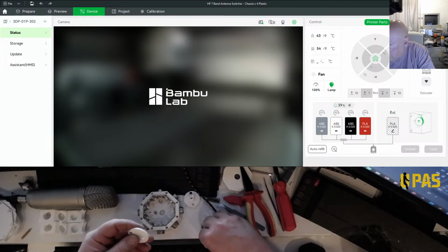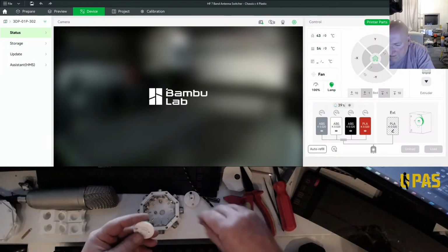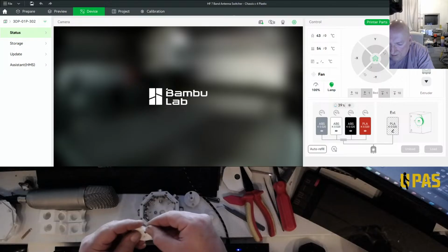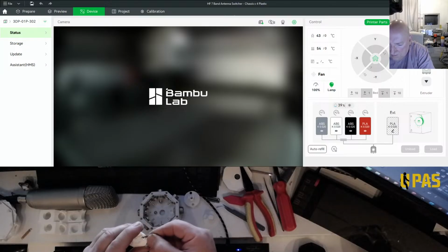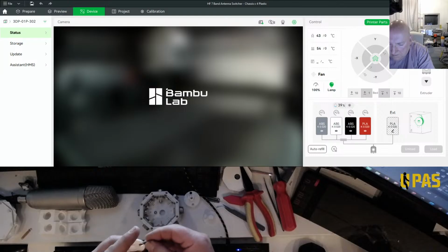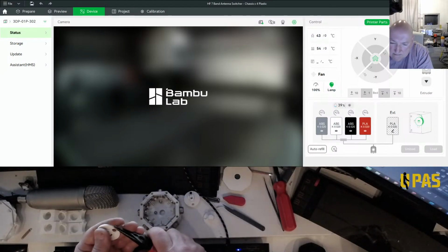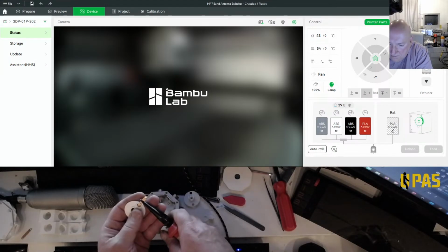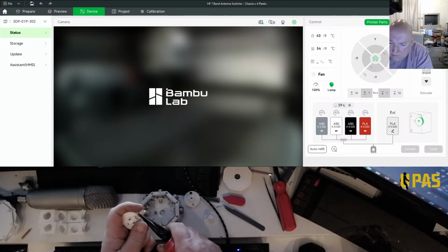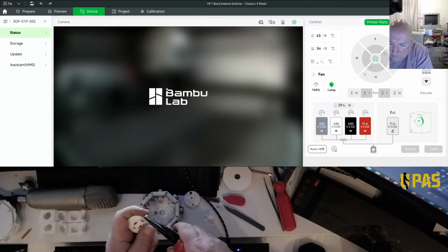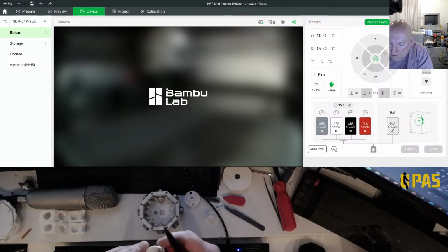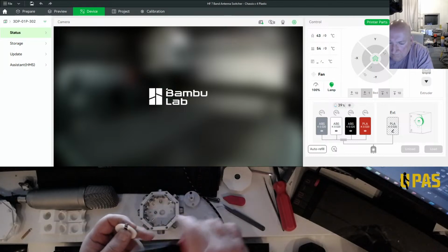So, just push that in there. Right, it's not going in. Why not? Let's force it in. Right, it's going in now. Look. You have to just inch it in. It's a tight fit 'cause you want a tight fit. Just inch it in at a time. Just enough to stick out the end so you can solder it.